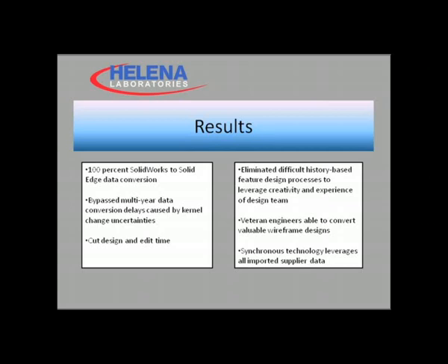Everybody knows that history-based modeling can sometimes be very tedious, especially with very complex, very large models, and with the regeneration problems and models blowing up. We'll now be able to salvage all the existing data we have in our product line, the wireframe modeler, and we can import any vendor data, STEP, IGES, whatever, and it's no longer a dumb solid like it was in SolidWorks.